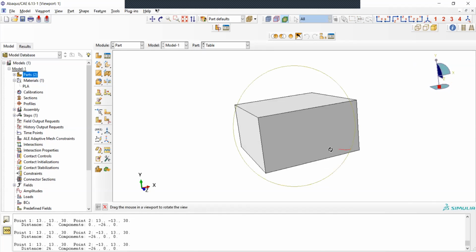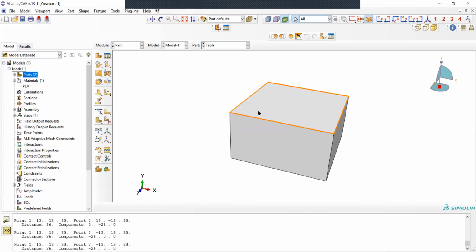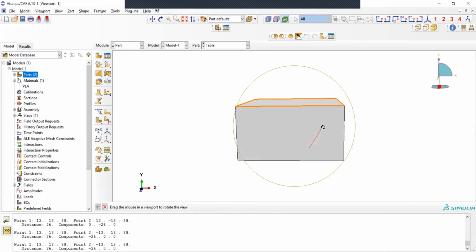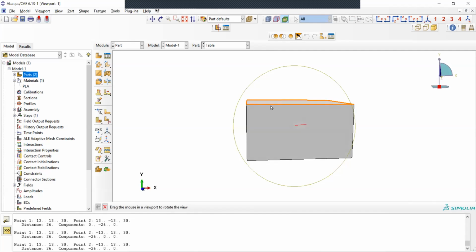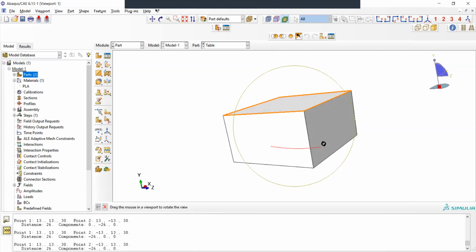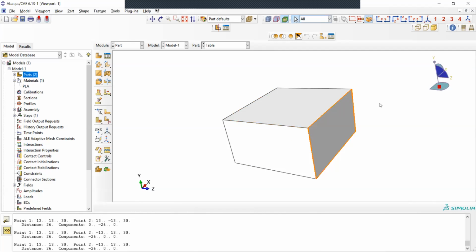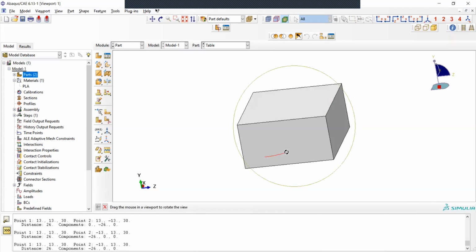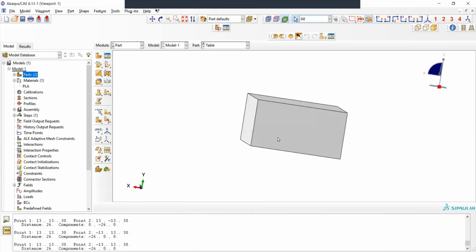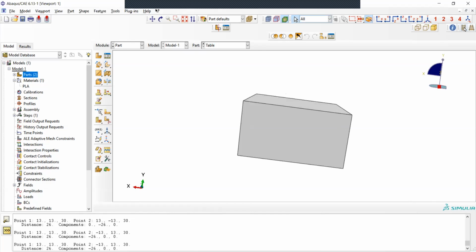from the other side. One small but important thing: you see the visualization. If I try to rotate this, it always looks like there are some angles. It's not perfectly flat, there is some perspective view, which is more aesthetic. So you should turn this off to see things as flat mathematical geometries without the artistic perspective. So just click here, and everything is now more geometrical engineering rather than artistic perspective.